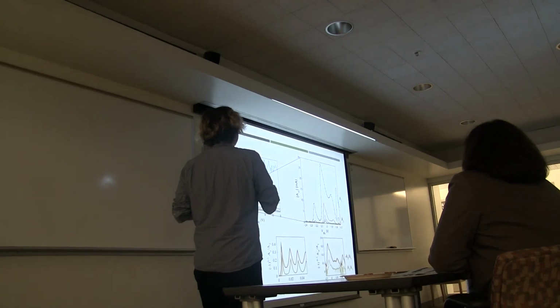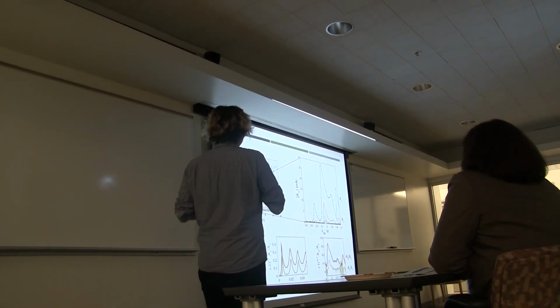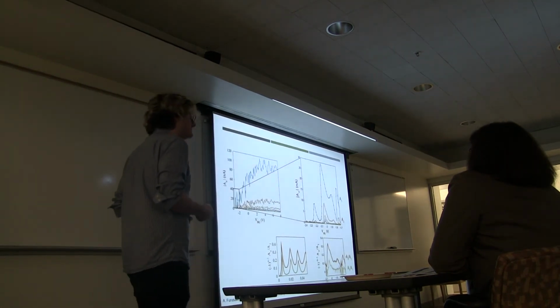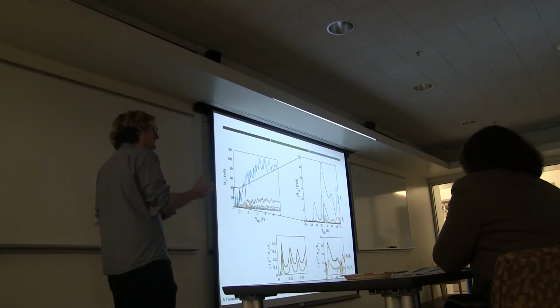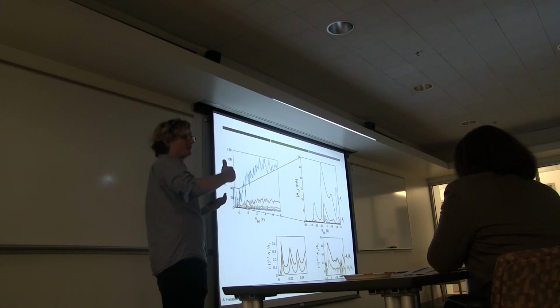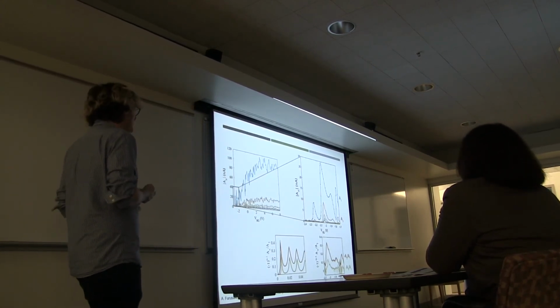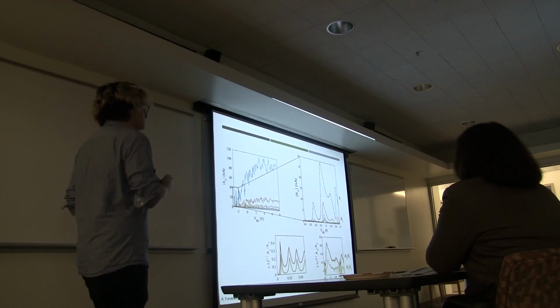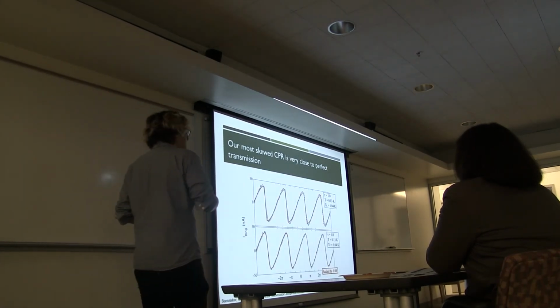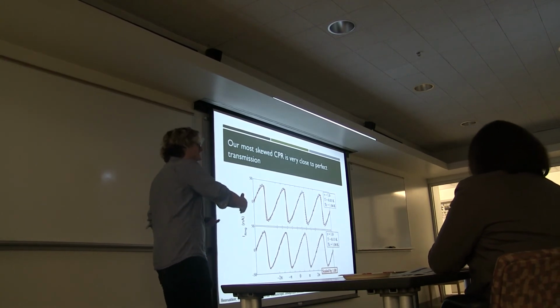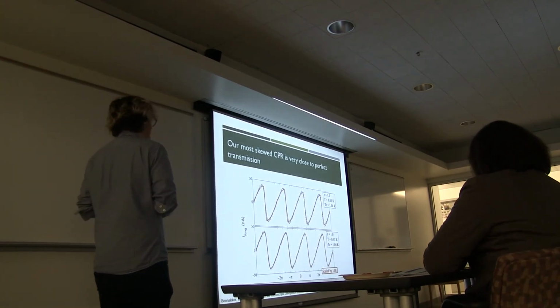I'd like to note that actually this peak here on the larger gate sweep is where we observed the most forward skewed current phase relation. So the most forward skewed current phase relation is weirdly just as the junction is turning on, where we'd expect disorder to be the most important, naively. And so I attribute this sharp forward skewness not to a really conducting or close to perfectly conducting mode. Instead, I think it's because of resonant tunneling.